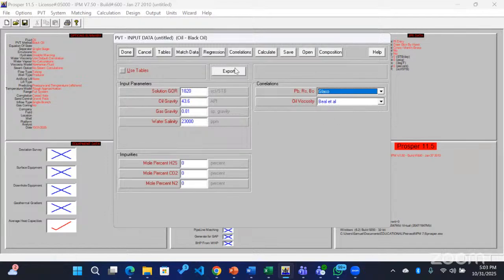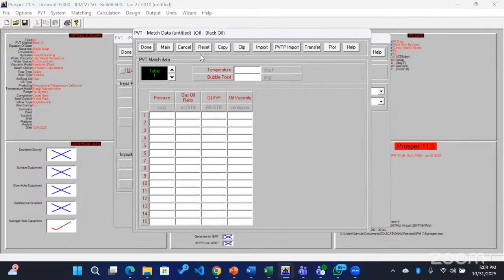So another thing that is very necessary is our laboratory data, because matching of data, especially in PVT, is very, very important. All these correlations, Glaso and others, carried out those experiments in very different locations, so it's important to do that comparison with what we have here. At least then we'll be able to select the best that fits our environment.